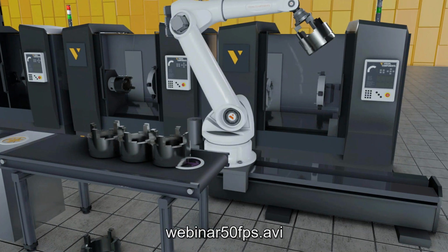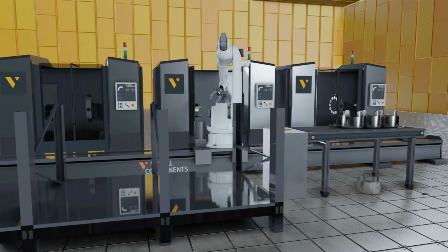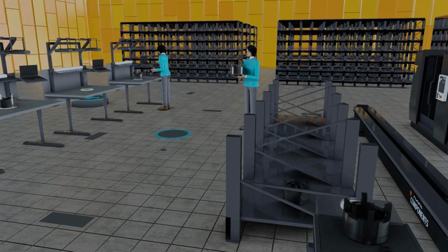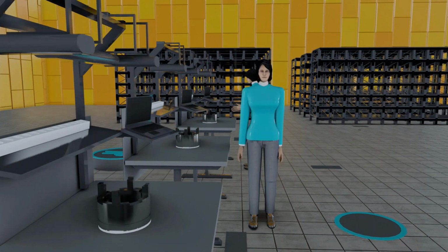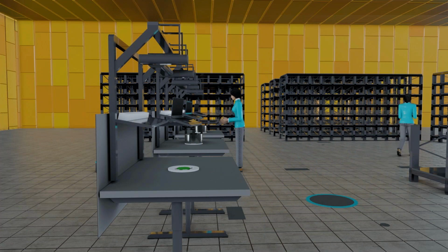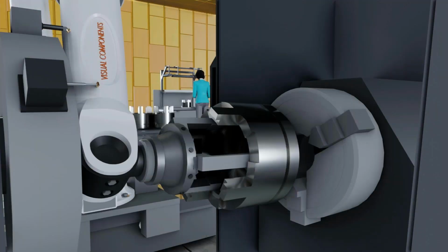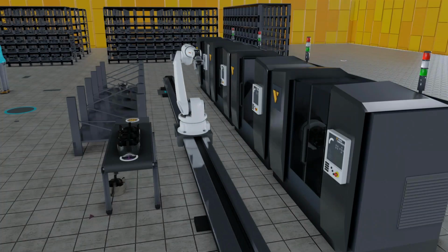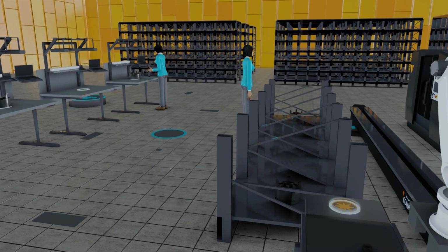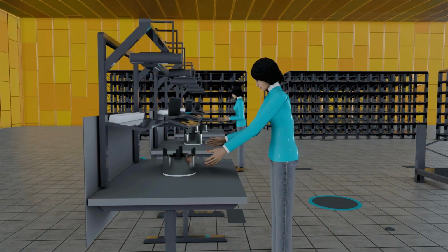Same kind of thing with the inclined conveyor, with the system helping prevent the drop of a product or a case if the slope is too much. And you can do physics-based simulation for this kind of case. Then you need to trial to see the accurate friction coefficient factors, or you could have, of course, warnings in certain components if you are planning to design incline-decline conveyors that are too high. The same could actually go for AGVs: if you're going downhill with the AGV with a big load, you should drive a bit slower. So this kind of things.